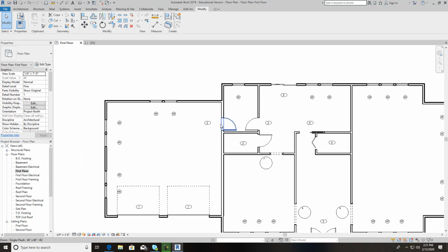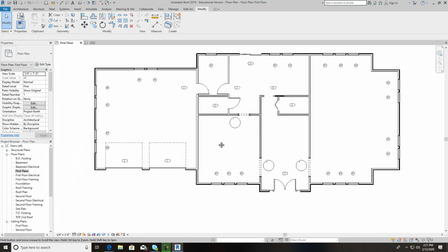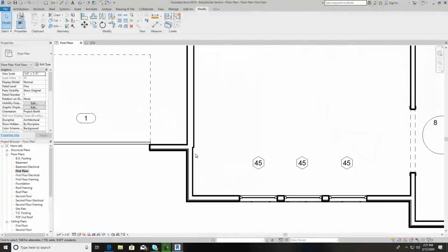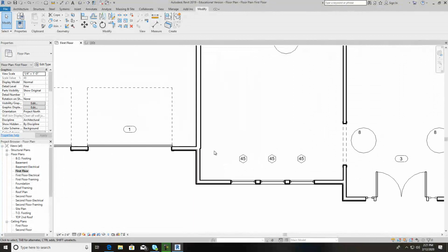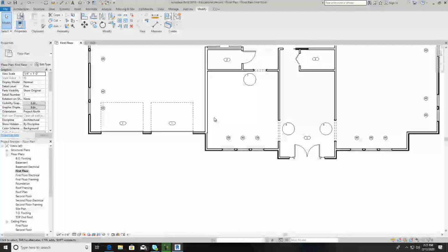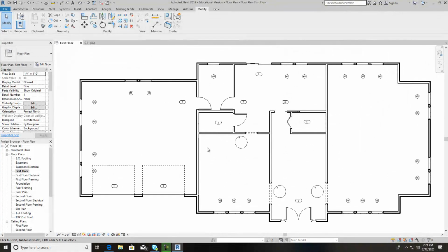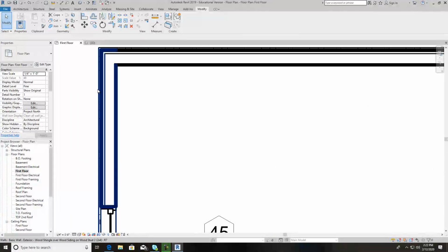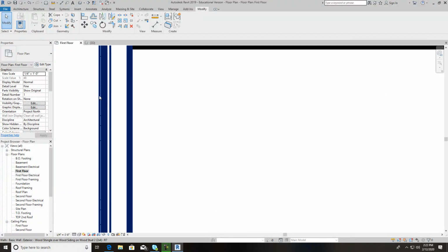But when I fix that wall, I noticed something down here, there's something wrong with these measurements. And we're getting ready to put the foundation in, and I want to show you something about measurements. Now, it's typical on exteriors, when you're getting exterior dimensions, you always go from the farthest point.